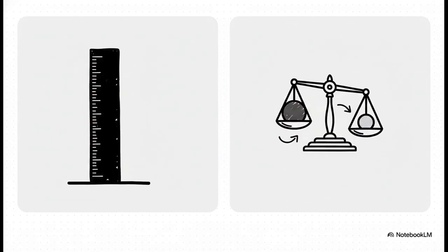Finally, we look at the baseline of the data itself. Is the reading absolute or is it relative? An absolute sensor reacts on a fixed absolute scale. So a thermistor, for example, is always going to read the absolute temperature. A relative sensor, however, measures a stimulus relative to a fixed or variable reference point. So when we measure pressure, it's very often relative to the current atmospheric pressure, which, as you know, changes.